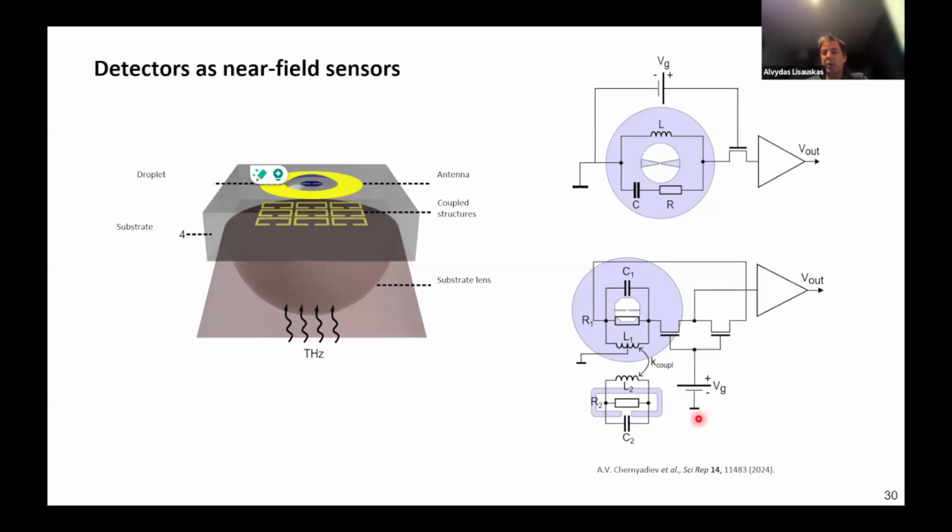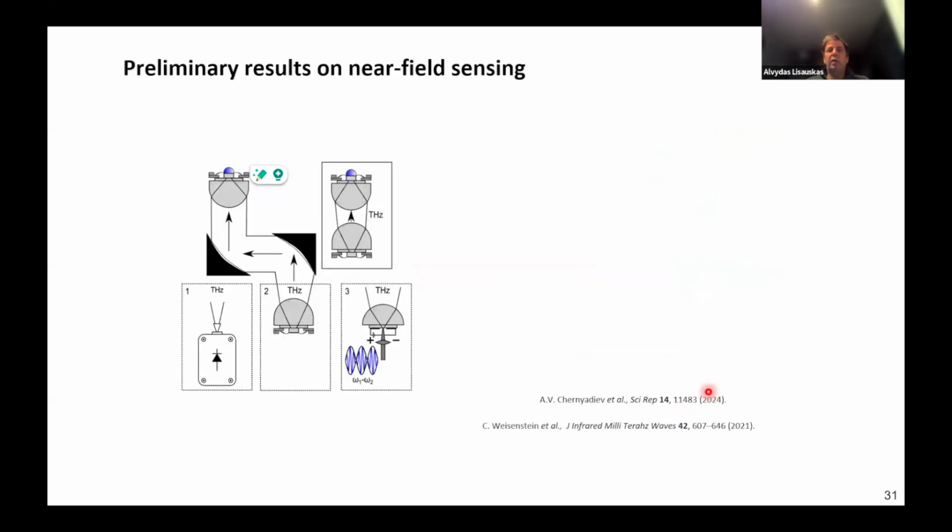We also implemented structures here, like coupling structures, and then enhanced metasurfaces, like 3D metasurfaces as well, to find out that, well, that's a concept of it, but in general you can use any external terahertz sources like a photomixer or VDI, and then use the detector with load, or we can use sources as small as possible. Another part of the discussion would be CMOS sources for terahertz. So one can do systems which are now extremely small and pretty capable of near field sensing.